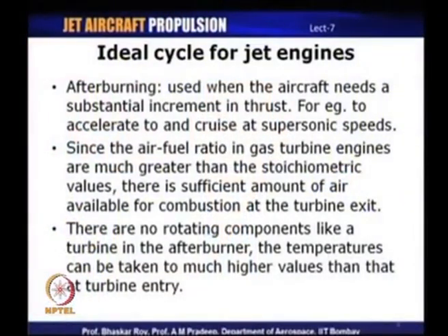So, with afterburning, there is a cycle which resembles a Brayton cycle with reheating. We have already discussed the Brayton cycle with reheating in the last lecture. Reheating is a process where we add additional heat after the first expansion process, which is exactly what happens in the case of an afterburning turbojet engine. That is, we add additional fuel and raise the temperature to a much higher level and expand all over again. So, a turbojet engine with afterburning closely resembles a Brayton cycle with reheat. We will take a look at the turbojet with afterburning or reheat as well.